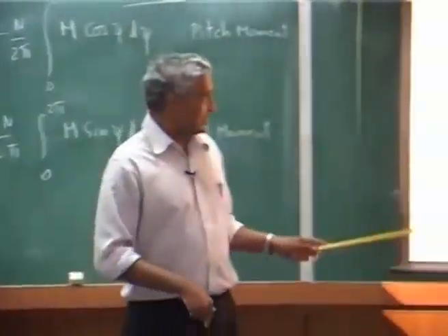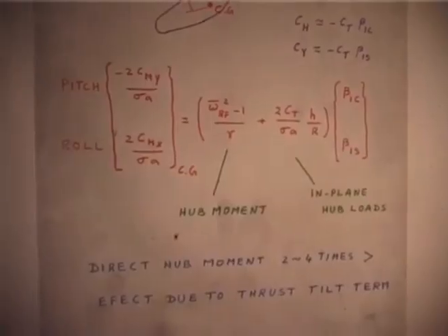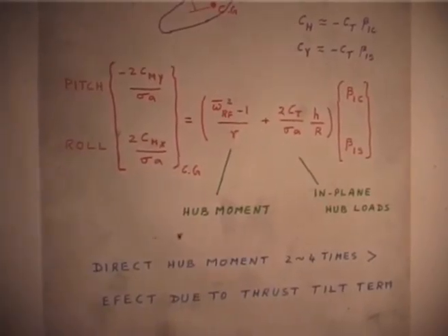But then if you keep on increasing the flap frequency, it will become highly sensitive, because any small change, immediately it will start rolling. Now, this is the trade off: whether you want a sluggish but stable vehicle, or you want a highly sensitive one, but highly sensitive again is subjective. So, when they go through the flight, they always ask the pilot.